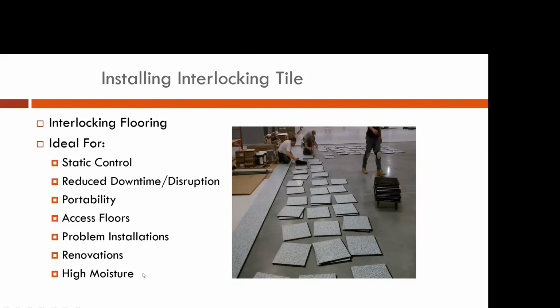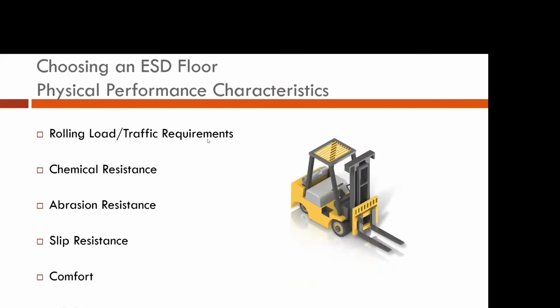Your physical performance characteristics, you've got to take a look at what is the type of foot traffic, rolling traffic, mechanical traffic that's going on top of the floor. How tough is it? How durable? What's the resistance that it's going to have as far as various chemicals? And again, the various applications, the various materials that you use will tell you what they can withstand and what they can't. If you have a floor that gets wet, and it's an epoxy floor that you're looking at, you're going to need to build treads into the floor. Can you do that? Will it still function properly as an ESD floor? Different materials have different criteria and different considerations.